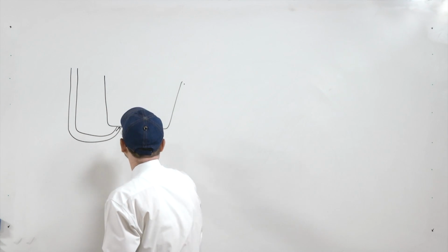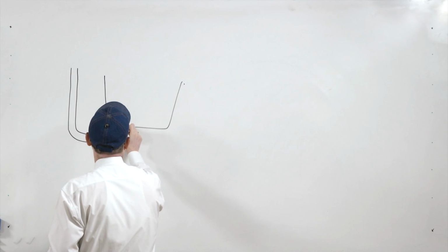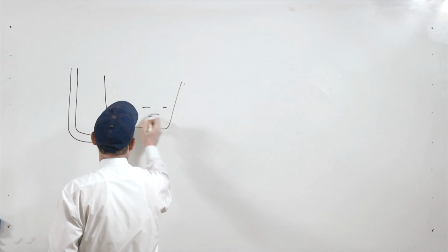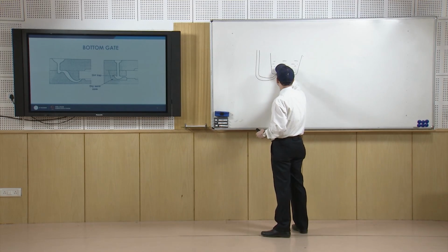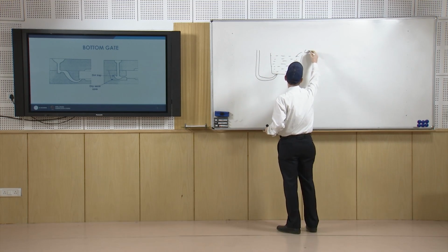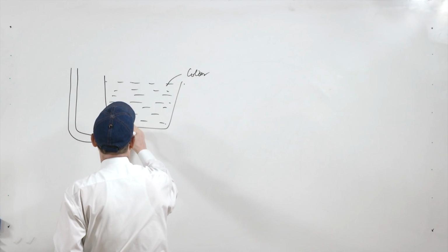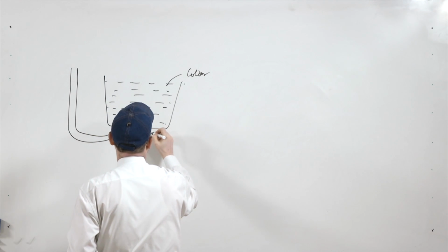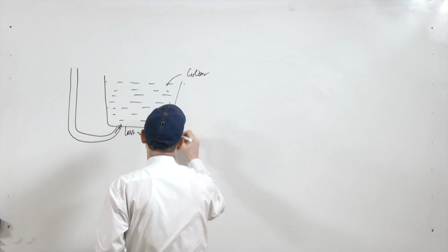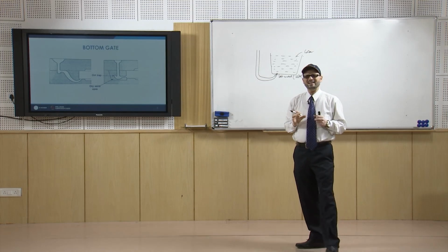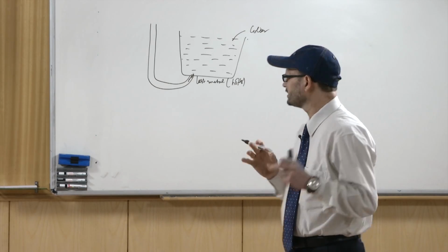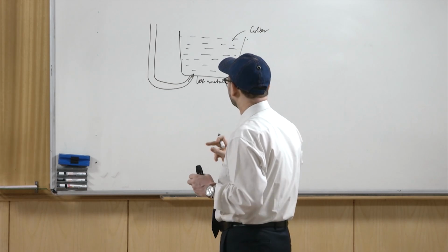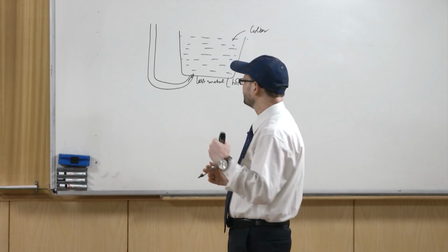So, what happens? The hot metal level will go on increasing. Now, the first metal which has come goes at the top, so it becomes colder, and the last metal which enters here is hotter. So, basically achieving a directional solidification is somewhat difficult in the case of these bottom gatings, but however it has other advantages as we have discussed earlier.